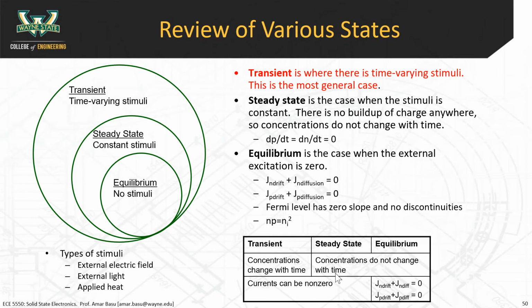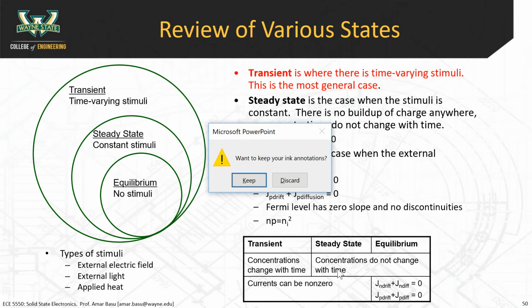Are you talking about the transient situation? No, the steady state. Yeah, in the steady state situation, in forward bias, what you're doing is injecting carriers. It's internal. It already exists. We did not get any external carriers. No, you actually are injecting carriers from the external circuit. Let's talk about that. So you say concentration did not change.